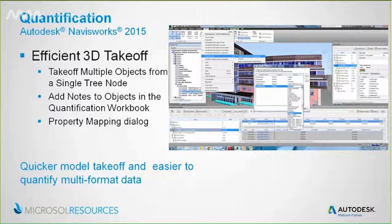There is one bullet there for property mapping. This is a feature that already existed, but it's been extended for products that fall outside of the traditional AEC workflow. I haven't encountered it personally, but from what I understand, products like Plant 3D may not necessarily have the property mappings that you would already naturally assume from an AEC product like Revit and NavisWorks, so if you want to map specific properties, you can. I'll show you that dialog, even though I don't have anything really to map, just so you can see where it is, those of you in industrial design and plant design, where you would go ahead and do that.